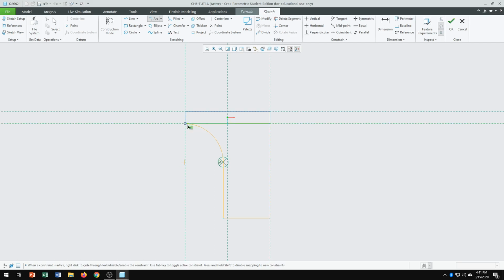We can just use the curve or 3-point arc, and the radius should be 31 according to the specification given. In order to see the pink shade, because the sketch is incomplete, we need to close the gap or the loop. Let me see. All right, one more time, we're going to do the line from there to here. It should give us the pink shade.